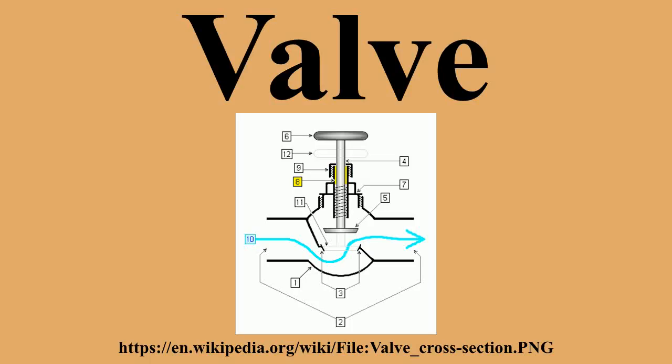Three-port valves. Valves with three ports serve many different functions. A few of the possibilities are listed here. Three-way ball valves come with a T or L-shaped fluid passageways inside the rotor. The T valve might be used to permit connection of one inlet to either or both outlets, or connection of the two outlets. The L valve could be used to permit disconnection of both, or connection of either but not both of two inlets to one outlet.